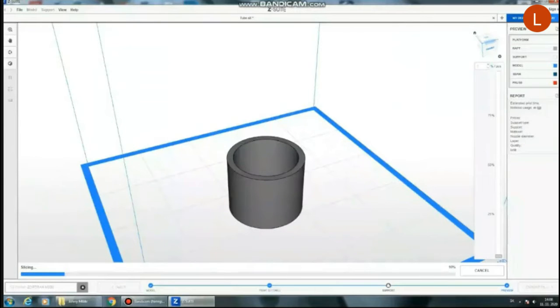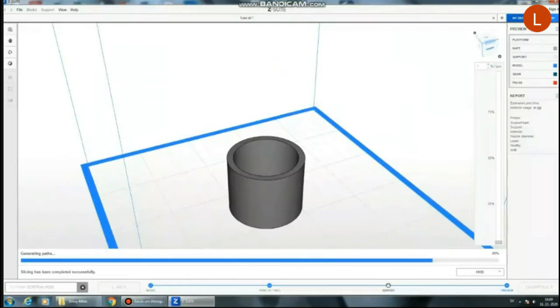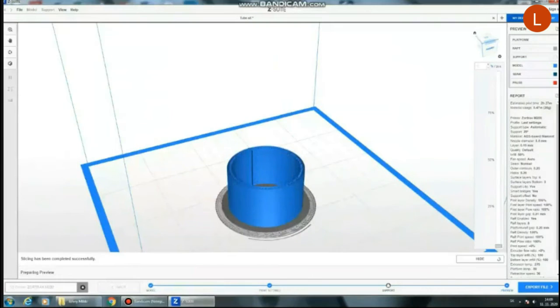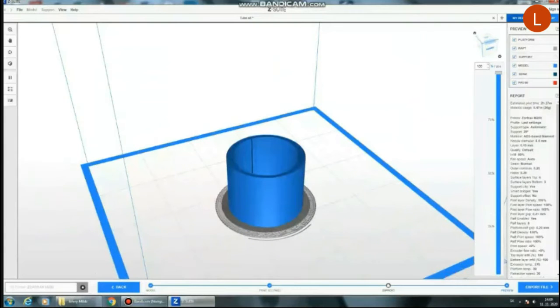After setting the production parameters, the simulation of the manufacturing of the part in the given software follows. In this phase of the simulation, the model is sliced into layers. This is necessary to generate paths for the print head for manufacturing the model layer by layer. The estimated print time is 1 hour 42 minutes. The material usage is calculated as 14 grams.